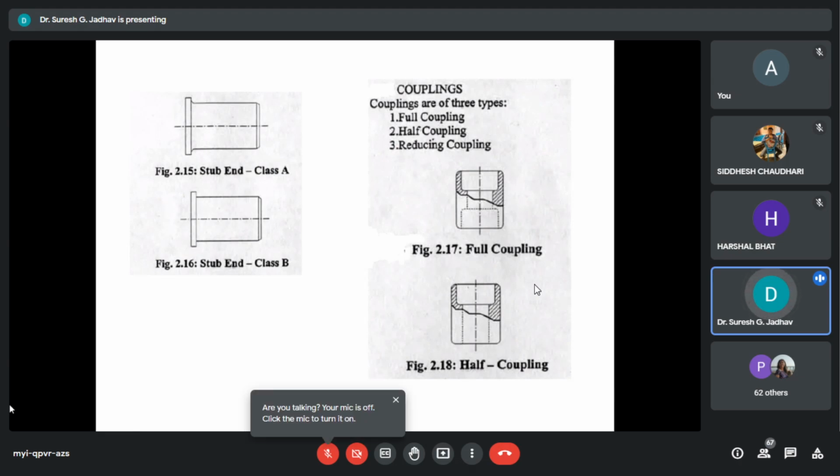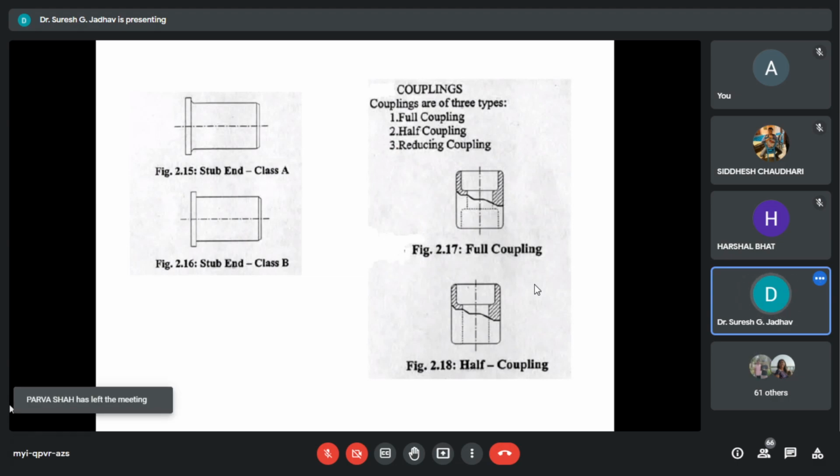When special facings such as tongue and groove, that is, male and female, are employed, additional lap thickness shall be provided.